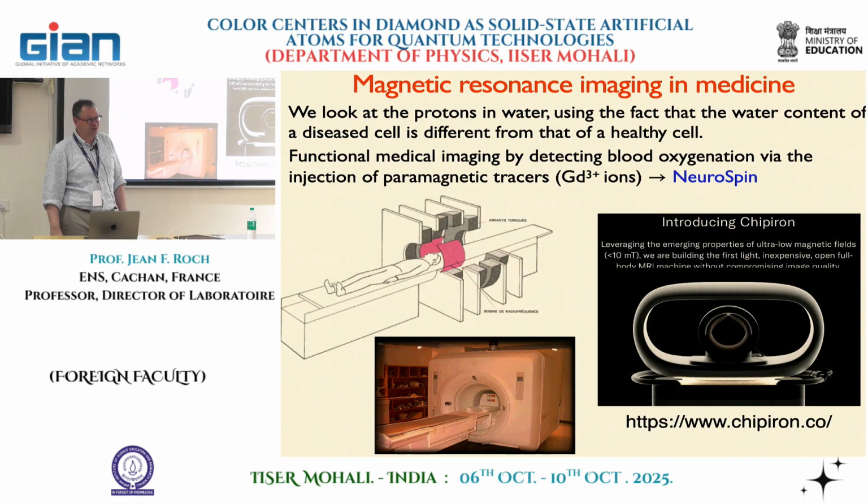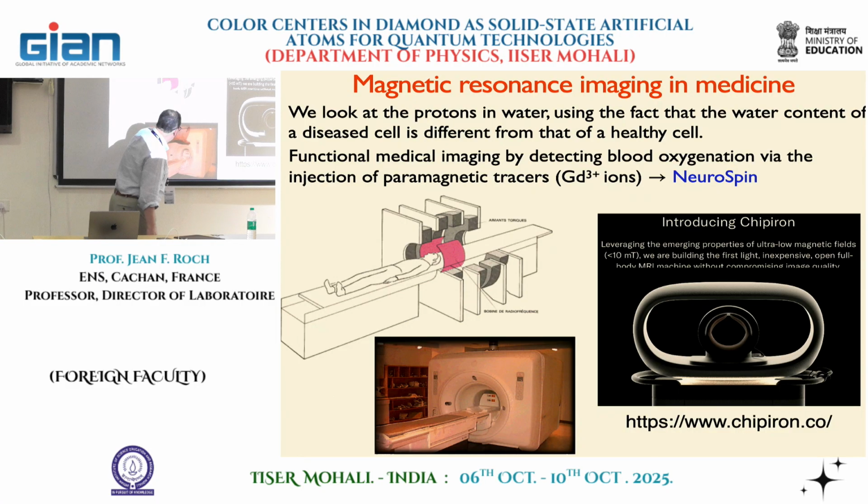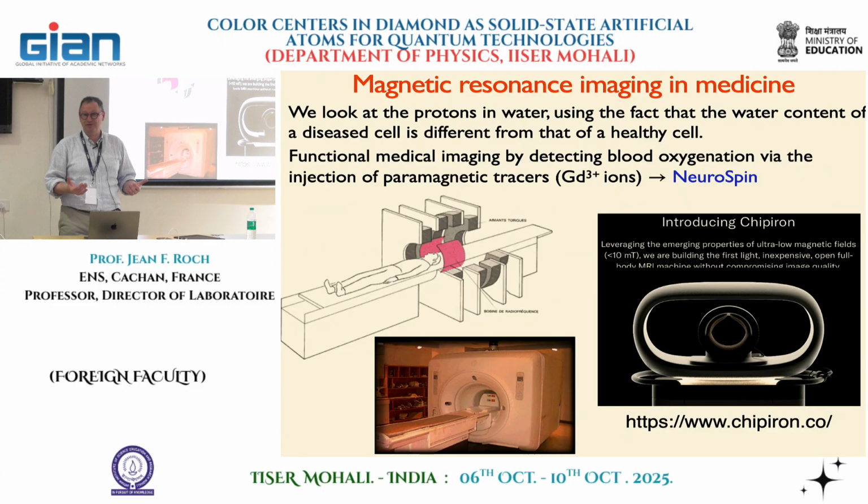And here, if you see, there is something here, just because if there is any problem with a superconducting magnet, of course, it heats up, and the helium that is required to get to the low temperature required for the superconducting magnet then immediately evaporates, so you need somewhere to flow the helium out, and this is usually what you have here.